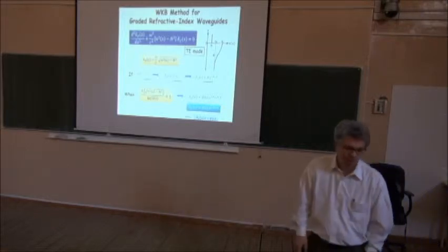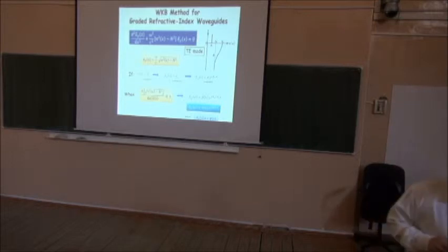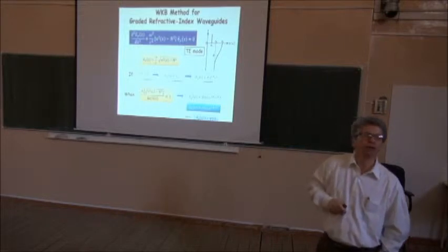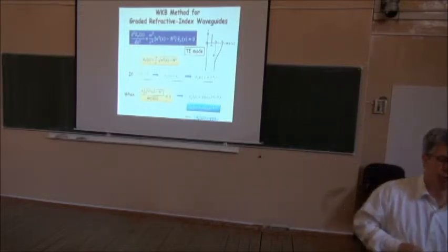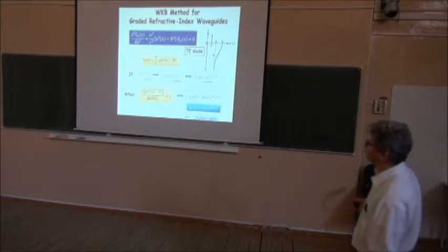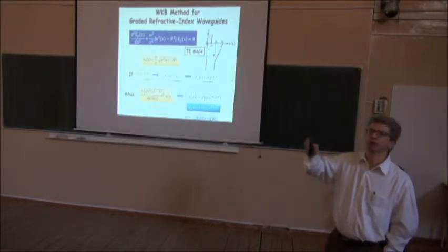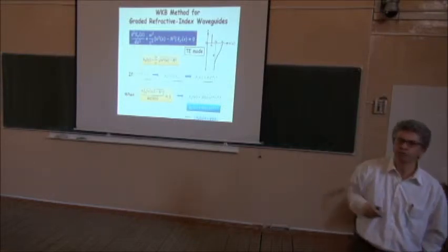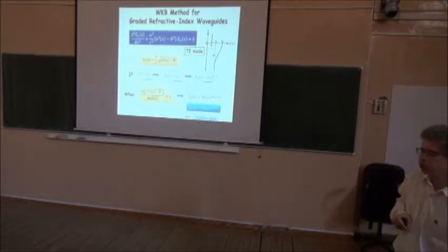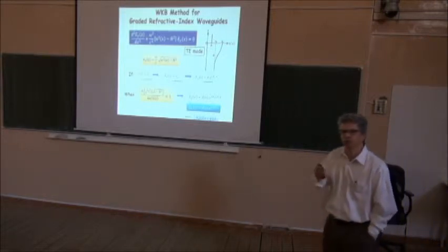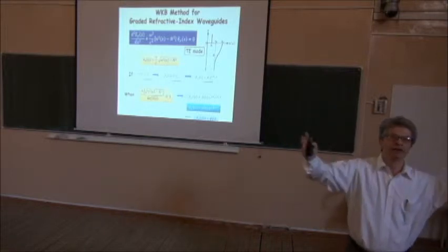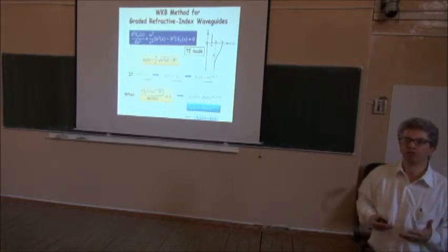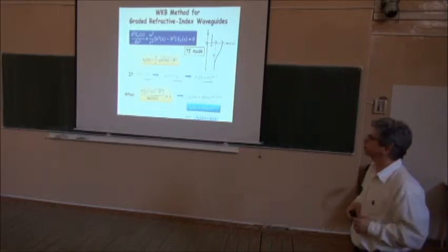Okay, so yesterday we studied step index waveguide, and then we started discussing a graded index waveguide that has a lot of technological importance. And as I mentioned to you, we used a very simple model, the ray optics model, to find the dispersion relation. But I mentioned to you yesterday that that model was insufficient to describe for us the electric field profile that we have on a graded index. And today we're going to use a more powerful approach so that we can get those results.